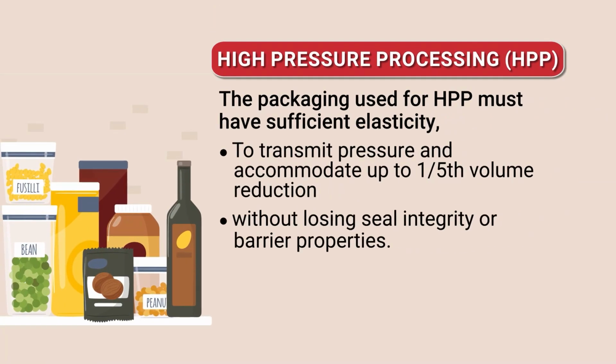I mentioned that this process is an in-container pasteurization kind of approach, where temperature is certainly not being used for killing microbes. Here we are replacing temperature with pressure. So the packaging material is very, very important; your package should be able to withstand that high pressure. We need a package which maintains integrity and barrier property during the processing, at the high pressure to which